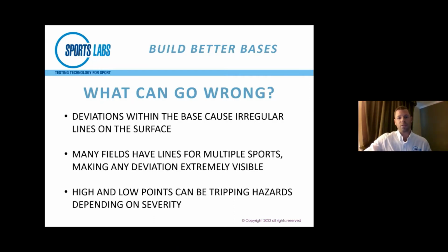If you don't get the base right, then it's just going to be visible on the surface, and there's no real way around that. And then beyond that, even safety, your highest and lowest points, depending on the severity, they can be tripping hazards. We've seen some pretty extreme examples of that, where these low spots, running along, you got a 16 millimeter dip, or an inch dip there. It can be a tripping hazard.